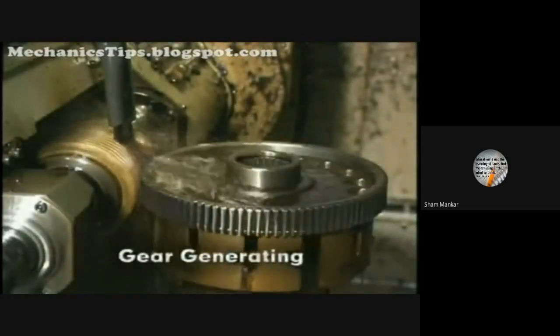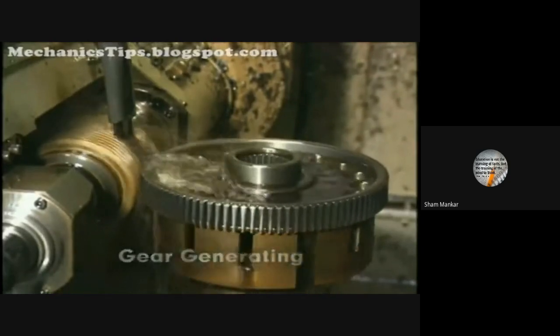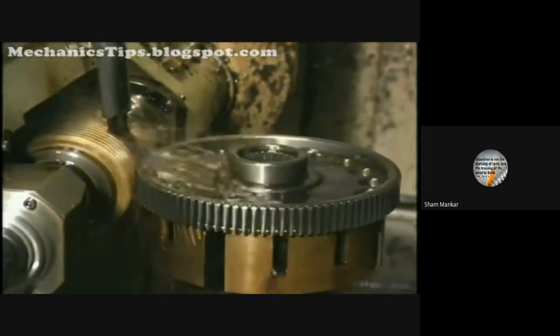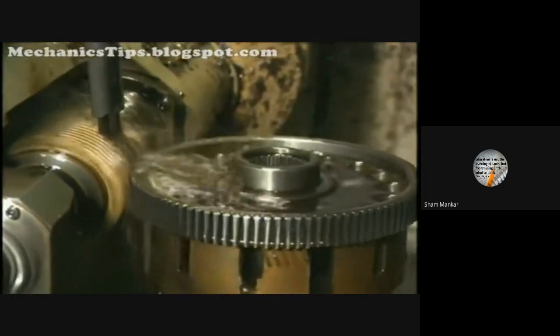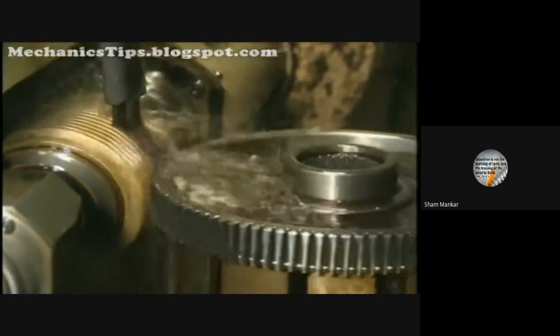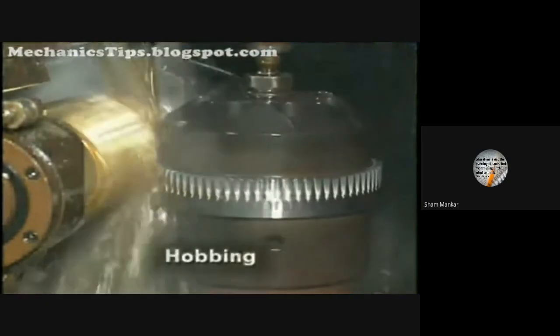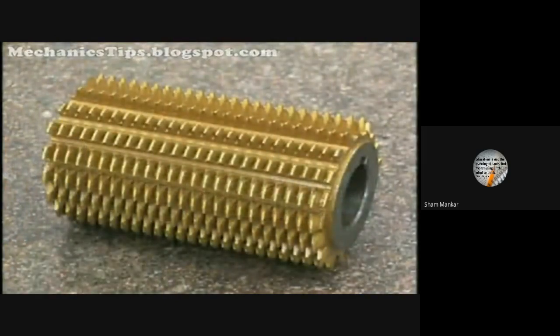Gear generating involves gear cutting through the relative motion between a rotating cutting tool and the generating motion or rotation of the workpiece. The primary gear generating processes include hobbing and shaping. In hobbing, gear teeth are progressively generated by a series of cuts using a helically fluted cutting tool called a hob.